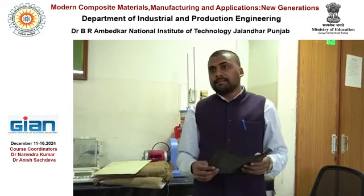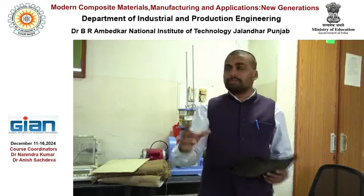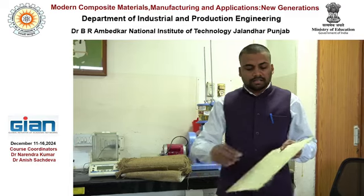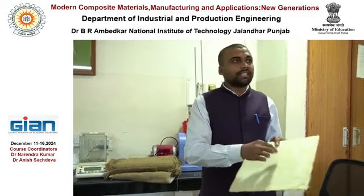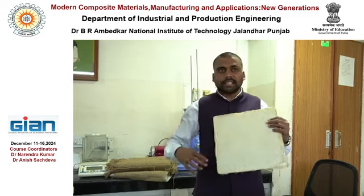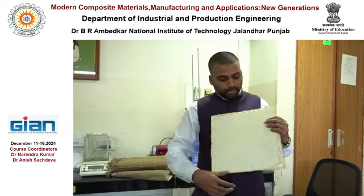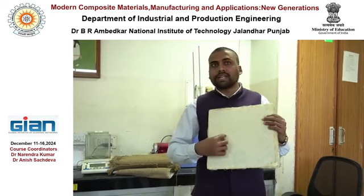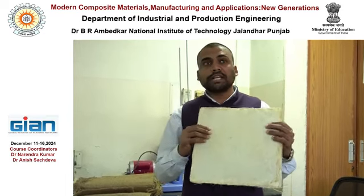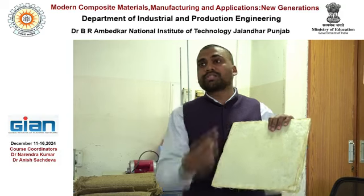And that air gap actually causes stress concentration. Let's say this is the composite material having voids in it. So what will happen under loading, let's say any type of load, tensile load or bending load or impact type of load, because of that void, that particular area becomes an area of stress concentration, and from there actually your failure starts.